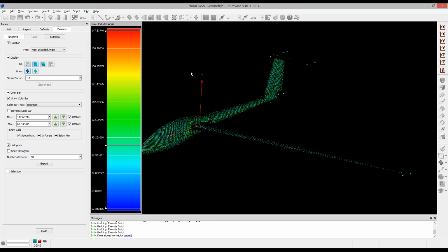One, you can just refine. You could change the topology. I would suggest changing the topology of the mesh. You can change up where the boundaries are, or you can just clip the geometry there and resolve that problem. But you should try to shoot for less than 150 degree max included angle for the quads and triangles that you generate on the surface.